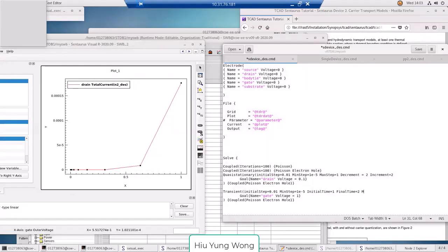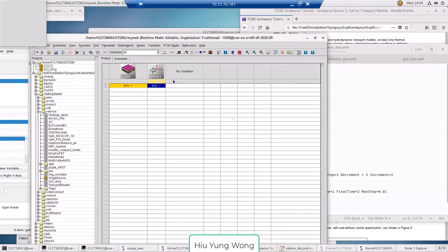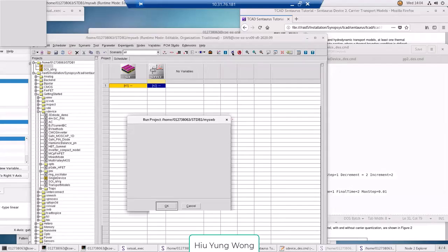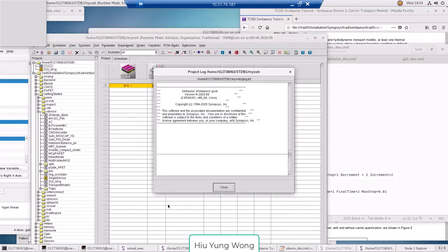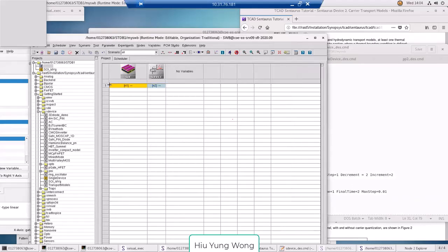We had a max step. Yes, max step. Now I go back to max step. Let's say I use 0.01. That will be very dense, right? It will take quite some time because it means it's going to take at least 100 simulation steps, right? Okay. So let me try that, or you can try that also. Now I make the max step equal to 0.01.